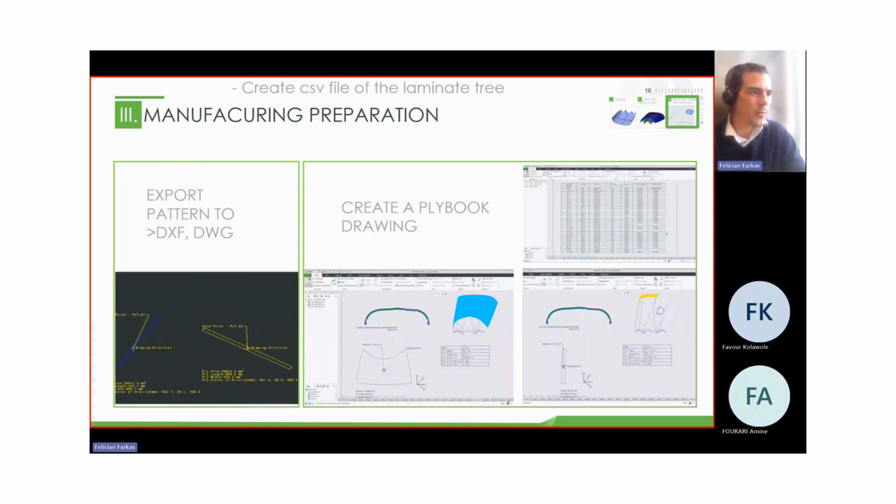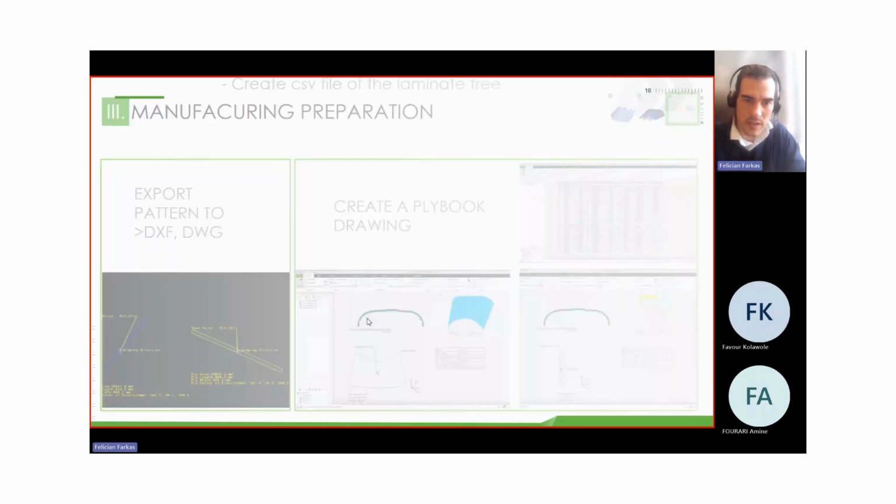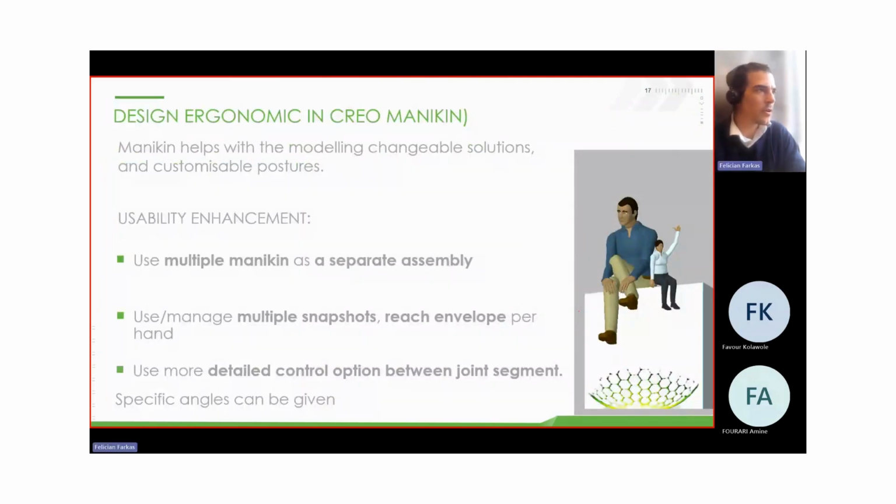So once we have these drawings, the machine is ready to cut the sheet to size. So you can see the flat version of the product, so it can easily be cut out, and once it's cut out, the drawing will also have the layout and the stacking order, also the orientation to carry out the physical work.